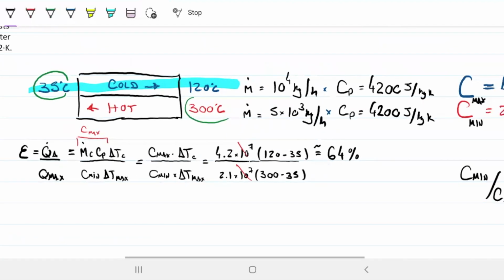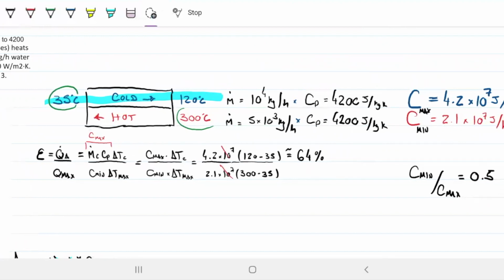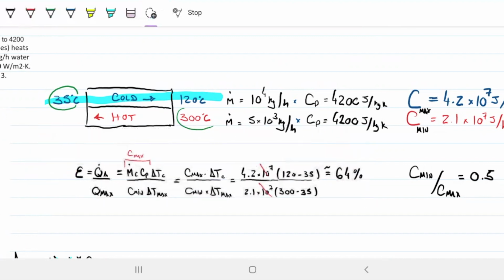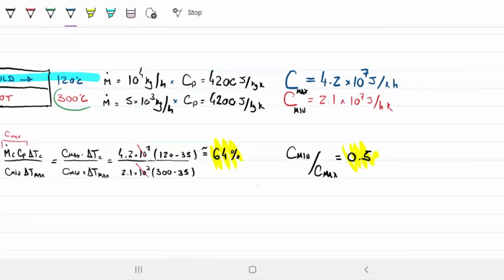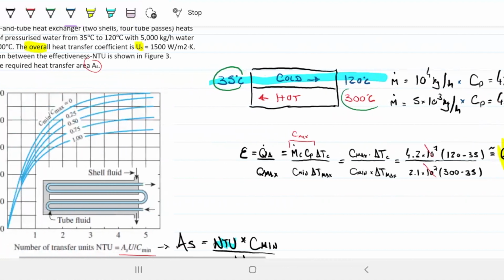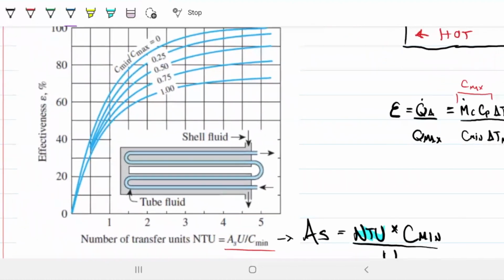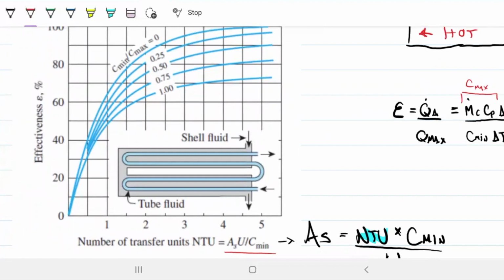Okay, so we're going to combine the two pieces of information that we gathered. We're going to combine this and this, and we're going to go to our graph, and with the combination of these two we should get our NTU, right? Let's do it. Again, disclaimer, I'm using a ruler on a tablet. This is not the best idea. Right here in the middle, 70%. So between the two, that will be 65%. If I do one tick closer, it should be the 64%.